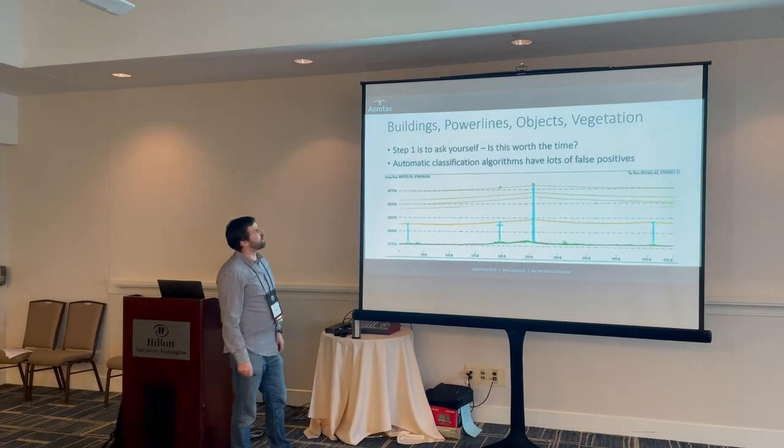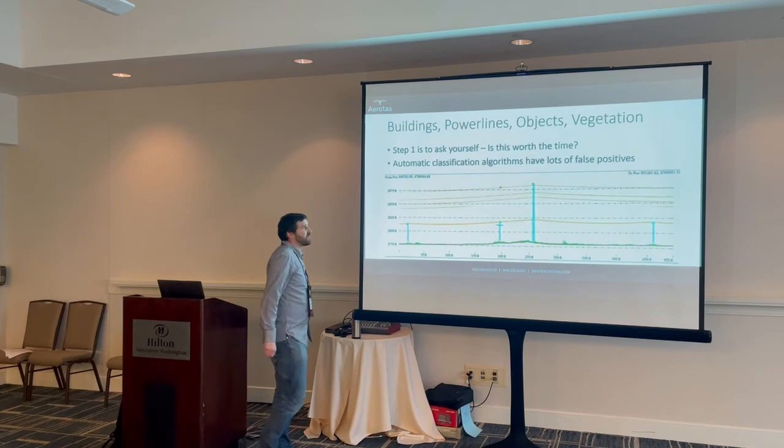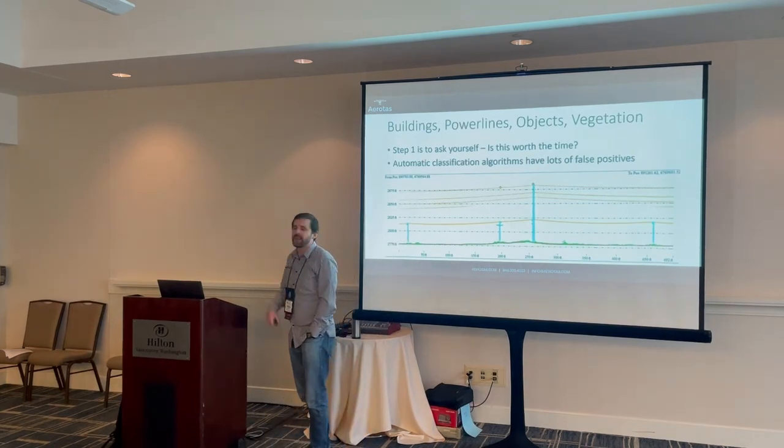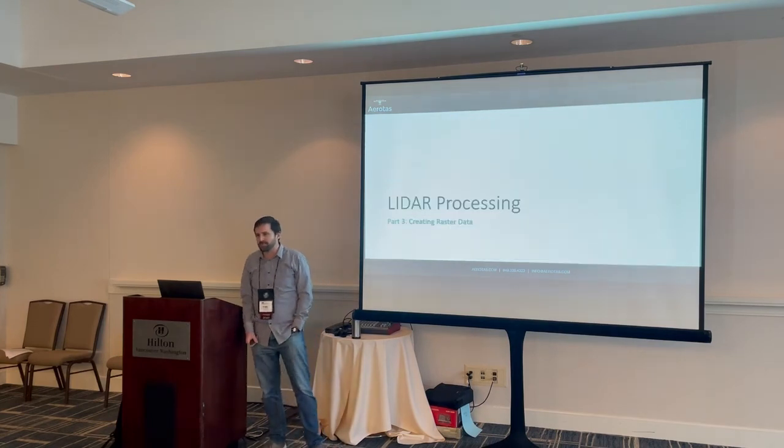And then buildings, power lines, all of that. Number one thing is ask yourself, is it worth the time? Automatic classification algorithms have a lot of false positives. We do start with automatic classification, but again, focus on ground. That's going to be the most important.